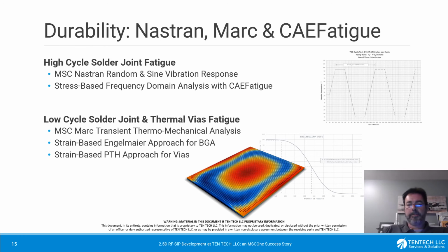So the fracture, the failure is much more pronounced and much more rapid. And this is all strain based. For most of the cycles we are actually creating plastic strain already, so we're plastifying most of the balls, or at least the corners, in many ways.